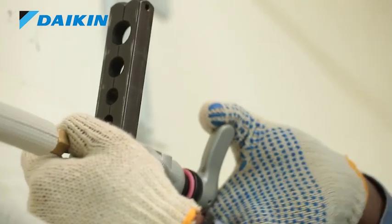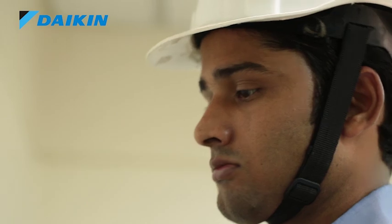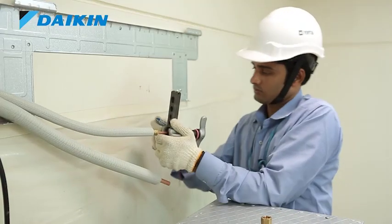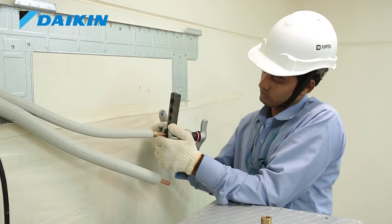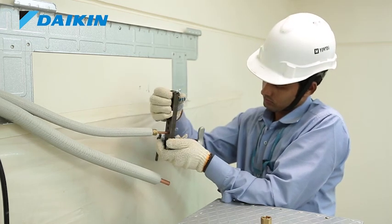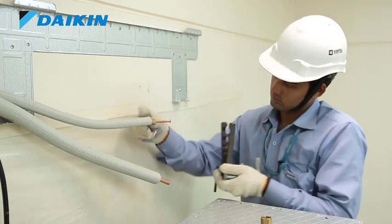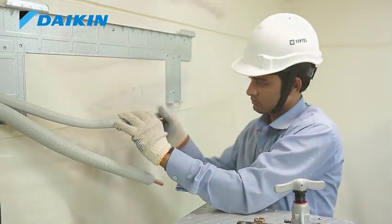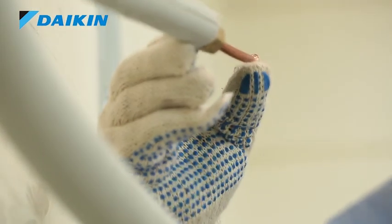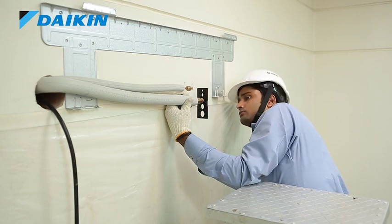Now, turn the handle anti-clockwise and remove the pipe from the flaring tool. Similarly, make the flare on the other pipe also. Inspect the flare surface for any crack or deformation. You can also use a flare gauge to check the size of the flare.